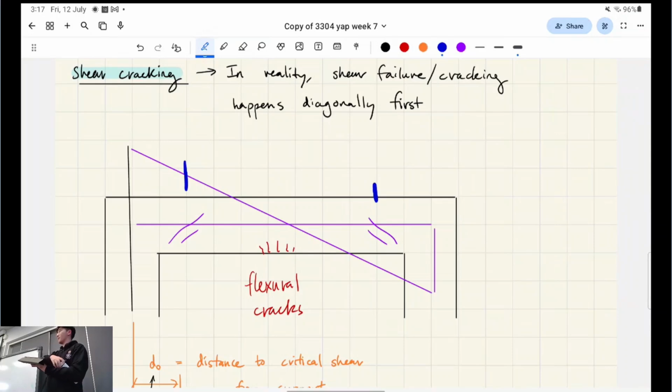Anyone want to give this a crack? Yeah, Ken. Is it because of the supporting beams? Very good. It's because it's rigidly connected, right? It's rigidly connected, and the columns are going to be able to help withstand a bit of the shear forces, right?